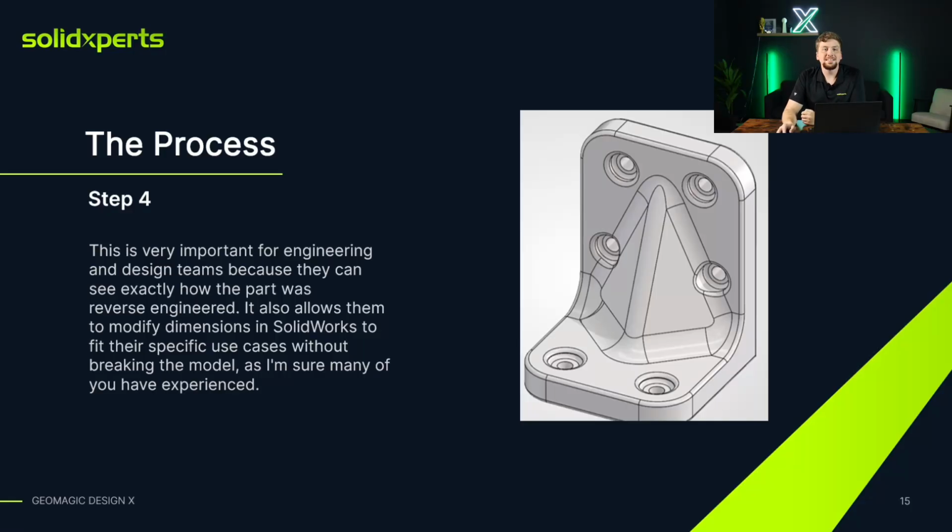It's very important to the engineering team to be able to see how you designed your part when you were reverse engineering it, because they're not going to ultimately see the mesh data, especially if you're working internationally, where one side has the part, one side doesn't have the part, and you are doing just long distance calls back and forth. That's always just a nightmare to deal with. So having that tree transfer over removes that middle part of, hey, why is this dimension like this? Why is this radius like this? Oh, he put in this dimension is 45 flat, it's not 43.333. And because in the deviation analysis, you can also shoot that over to them and show them exactly why you did that.